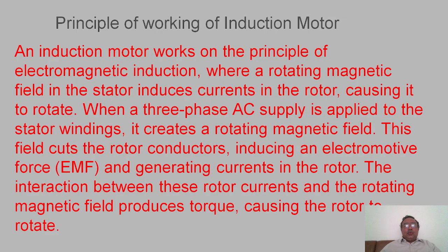Now after going through the construction, let's come to the principle of working of the induction motor. As in the case of a transformer, here also it is the principle of electromagnetic induction, where as soon as you give a supply to the stator winding, it produces a rotating magnetic flux. Now this rotating magnetic flux cuts the rotor bars or rotor windings, and being short circuited in nature, an EMF is produced and also an induced current is produced. Now this induced current will also produce a flux, and this flux will interact with the rotating magnetic flux, and thereby a torque is generated and the motor starts rotating.